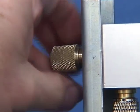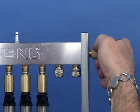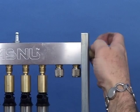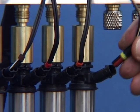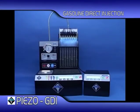Now refit the fuel rail retaining bolts to the left and right of the fuel rail. Once again, these only require finger tightness. This time, when fitting the ASNU 604 injector harness, ensure that the red insert on the plug is correctly facing downwards.